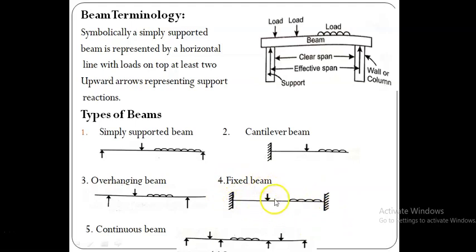In this case it is carrying only vertical forces, and therefore we simply neglect the horizontal reactions, because this beam carries only vertical forces and nothing horizontal is produced. Therefore this fixed beam has totally 4 reaction components: 2 vertical reactions and 2 reactive moments.